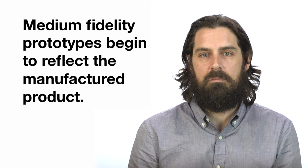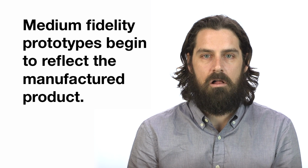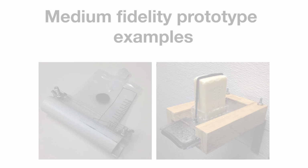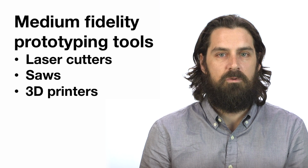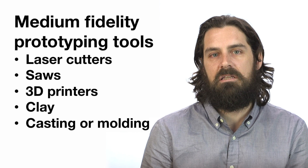With medium-fidelity prototypes, aspects of the prototype begin to reflect the manufactured product, but not all aspects. So what does a medium-fidelity prototype look like? A medium-fidelity prototype holds its shape, it's at the correct scale, and the main elements and functions are represented. Making a medium-fidelity prototype may require some additional knowledge of the making process, and some tools used for medium-fidelity prototypes include laser cutters, saws, 3D printers, clay, and molding. Medium-fidelity prototypes definitely take more time to assemble than low-fidelity prototypes.